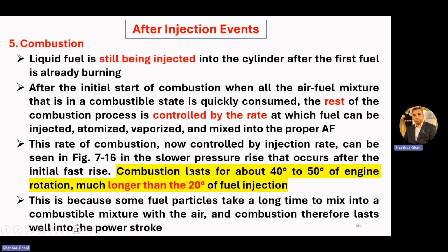This is because some fuel particles take a long time to mix into the combustible mixture with the air, and the combustion therefore lasts well into the power stroke.